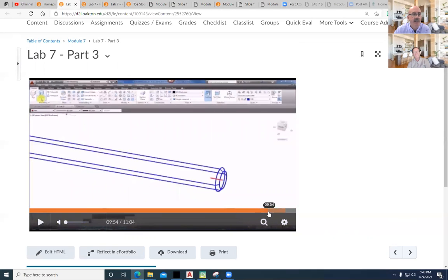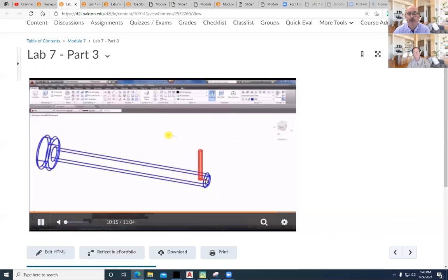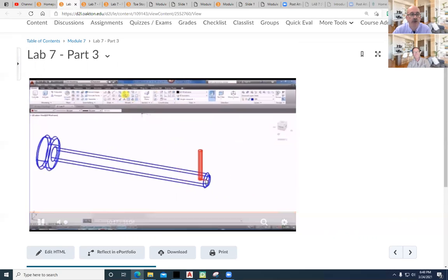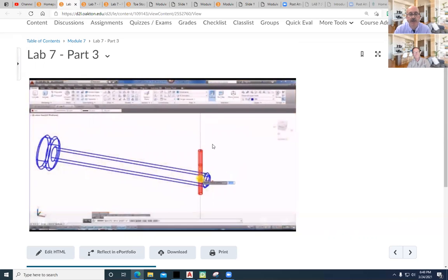And then I show some techniques for putting in a couple of pins. And so here's how you enable that pin. I use a 2.5D approach where I'll use a top view and create a construction line with a circle, and then I'll extrude it. And then I'll use a 3D move command to push it into the part, and then I'll subtract it.